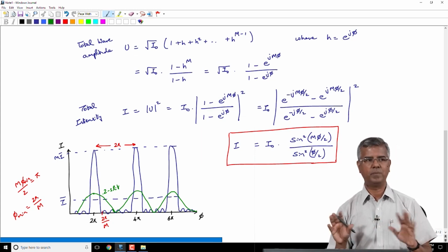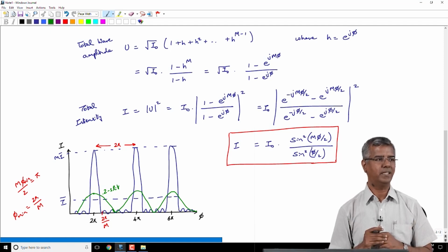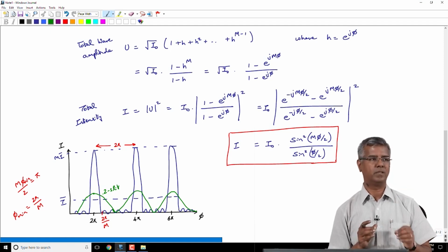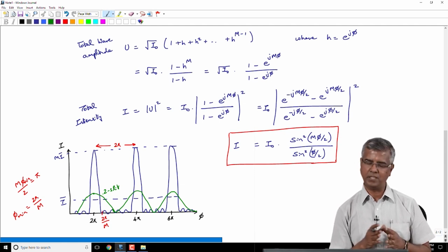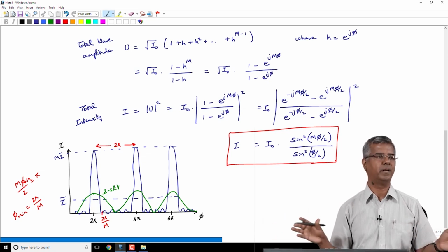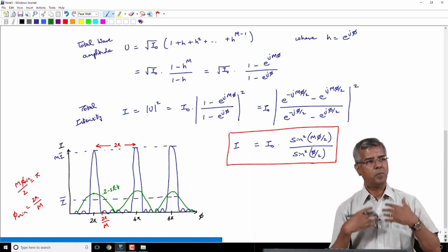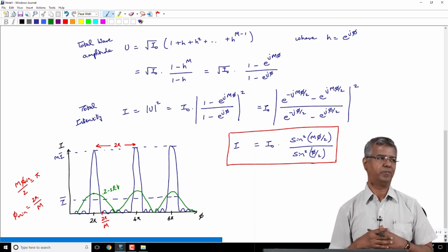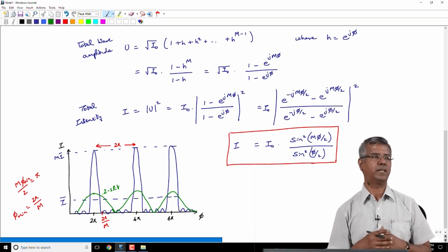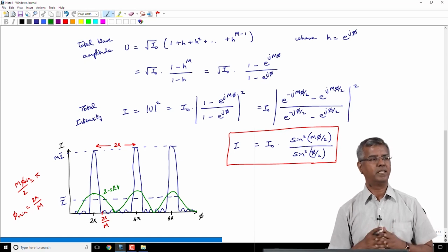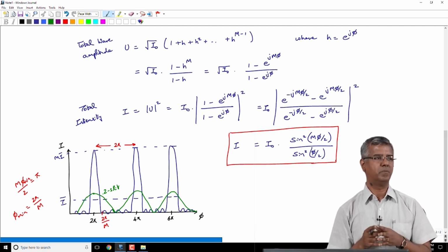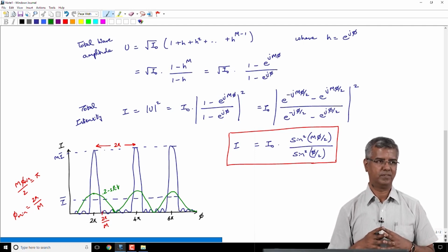Now, you say, no, in my application I cannot have that. I want to pick one particular color, one particular shade of a color very precisely, okay, and I don't want any interference from any neighboring shades, okay. Then what this tells you is, you go for a multiple component interference. So, with more number of sources that are interfering, the resolution with which you are picking up a particular color is going to be much higher, okay.